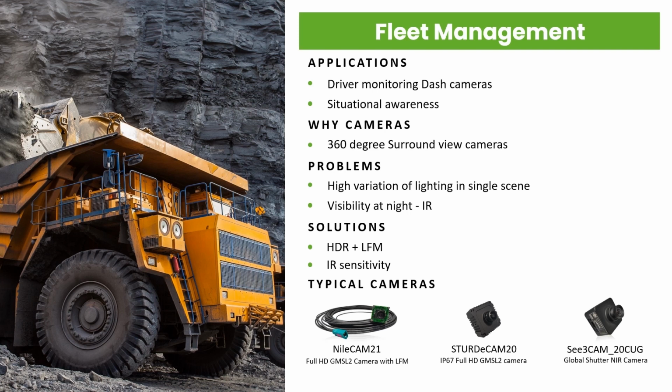Did you know that large goods vehicles, otherwise called heavy goods vehicles, contribute to over 63% of the fatalities in London? This is why the direct vision standard has been in effect across London since February 2021. This safety standard will apply to more regions in the coming months. The direct vision standard, otherwise called DVS, measures the driver's view through the windows of a LGV cab. The level of visibility is denoted by a star rating system as per DVS.